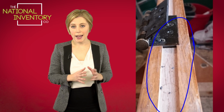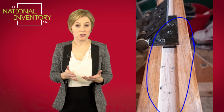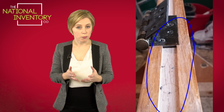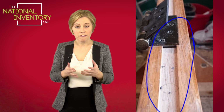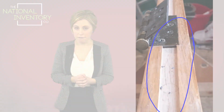The picture on the right-hand side is of a residential fire door. Now, the blue circle indicates the intumescent strip that's currently missing. This strip is important as it creates a seal between the door and the frame, stopping smoke and allowing the full 30 or 60-minute window for the fire brigade to rescue you. If the intumescent strip is missing, it could result in the loss of life.